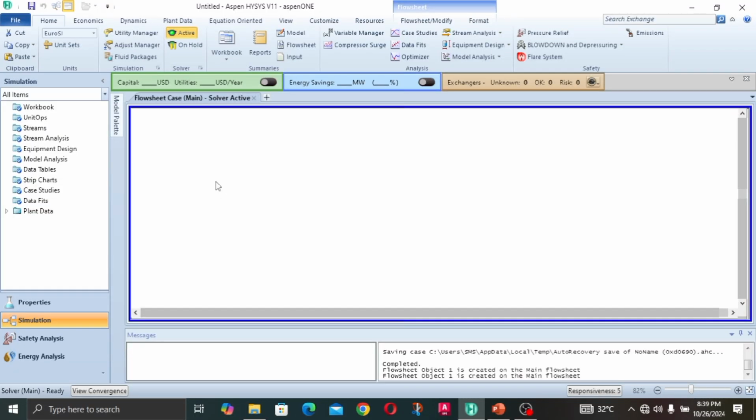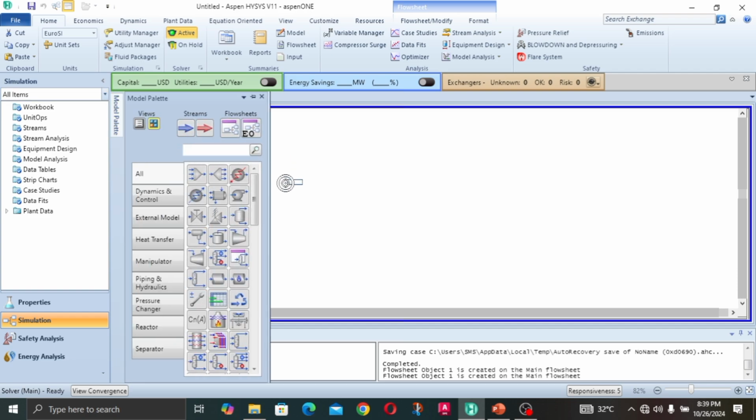We're back to the modeling environment to see what a pump looks like in action inside ASPEN HYSYS. Remember, the first thing to always do before you start simulating and modeling in ASPEN HYSYS is to select your component list and fluid package. If you do not know how to do that, the link will be dropped in the description. As always, please make sure to watch your previous content to avoid getting lost. For today's content, our component will be H2O, water, and our fluid package, as always, the very versatile Peng-Robinson. So we start, as always, by dropping a stream,